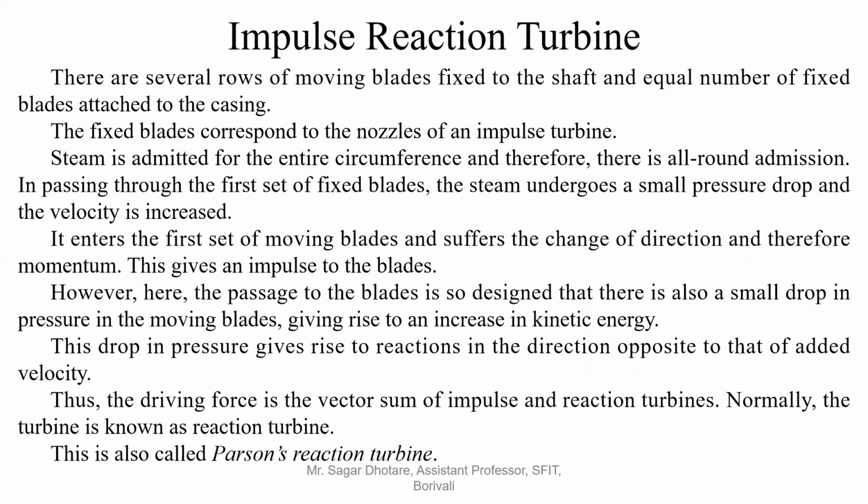Basically the working is a mixing combination of both, that is impulse as well as reaction. There are several rows of moving blades fixed to the shaft with an equal number of fixed blades attached to the casing.